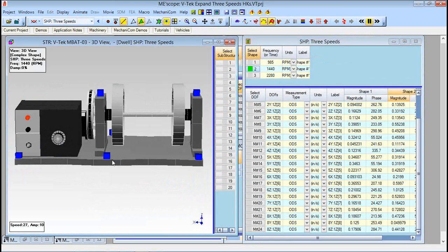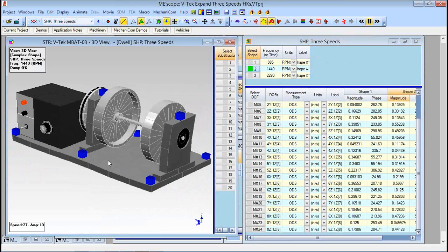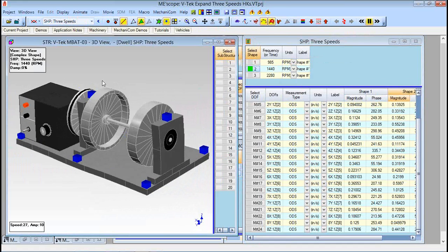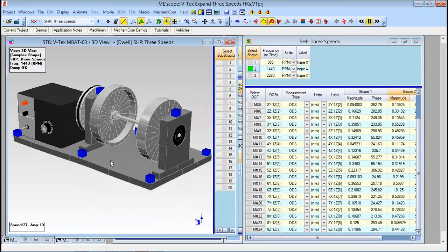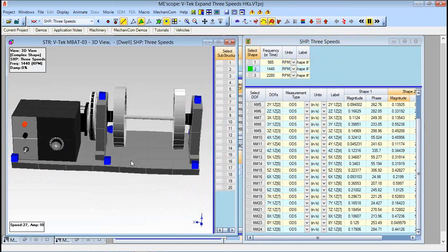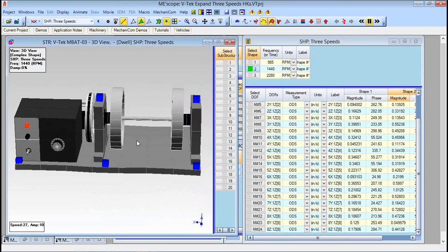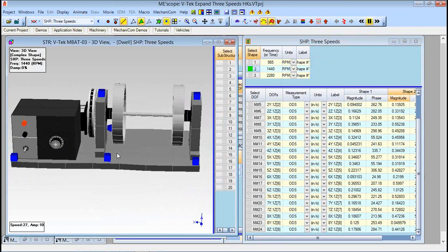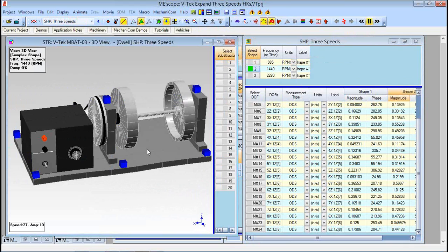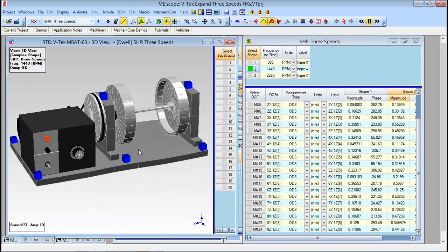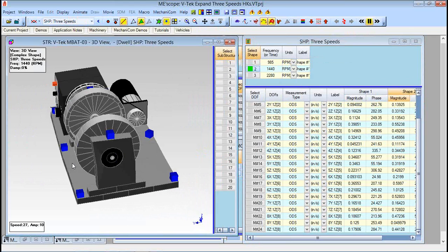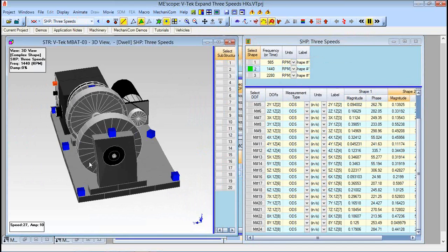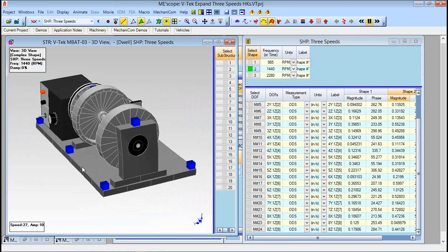But generally speaking, the way the interpolation is set up is that we take the motion of the 8 accelerometers themselves. In this case, we take the bearing blocks first and animate the shaft, and then turn those animation equations into measured, and interpolate the rotors from the shaft so that they follow it, all 3 of these rotors, including the pulley, and work through the model one substructure at a time to set up the animation and also the rotation. I'm not going to go into all those details today.